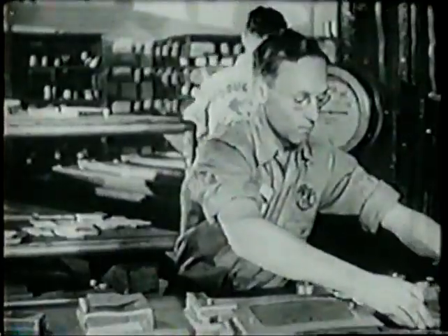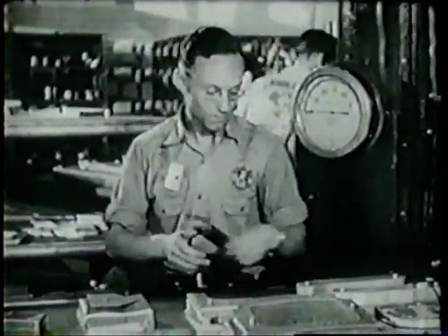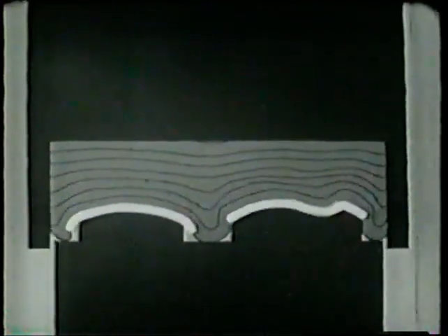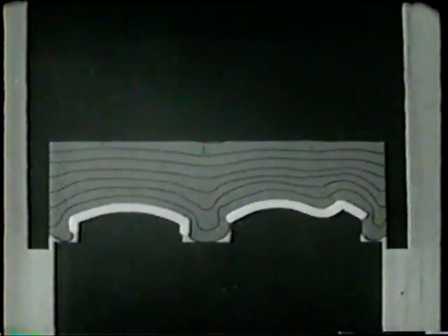The bending or shaping to double curvature of a number of parts at once is accomplished by use of a hydropress. The parts to be formed are loaded on a table, the alloy sections being placed on forming blocks or dies. The table is moved under the press, the action of which is single and continuous. The action of the hydropress is based on the use of a rubber blanket in place of the upper die. When it is brought down upon the loaded table, the rubber pad transmits pressure in a fluid-like manner, forcing the metal to the shape of the dies.